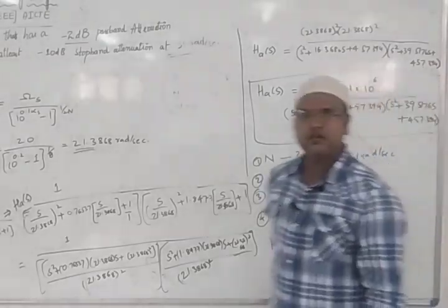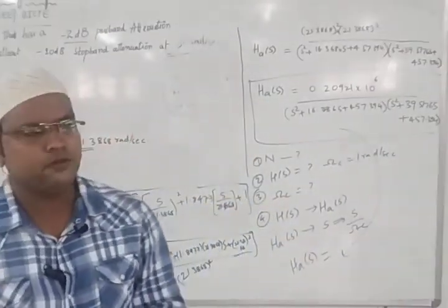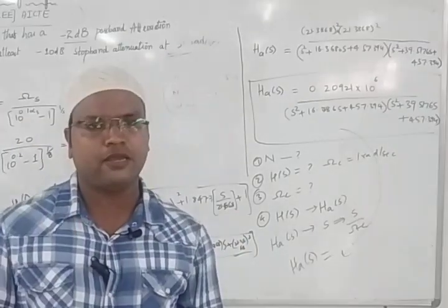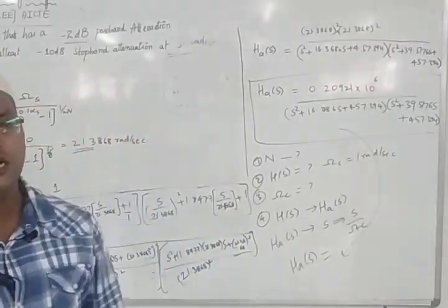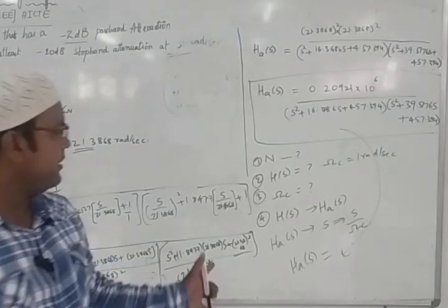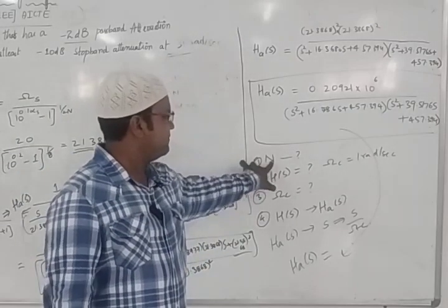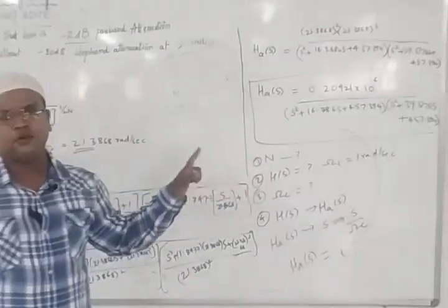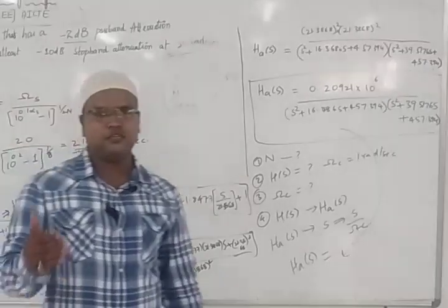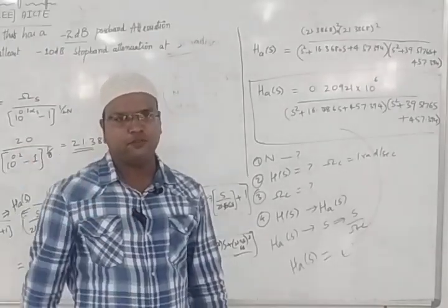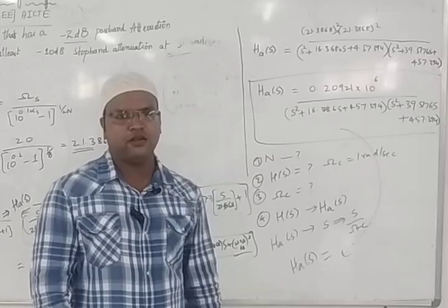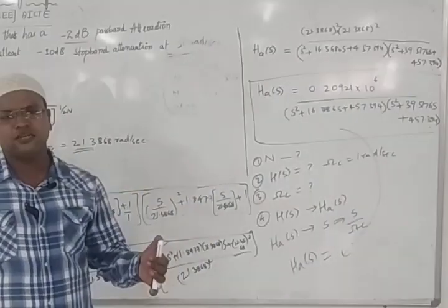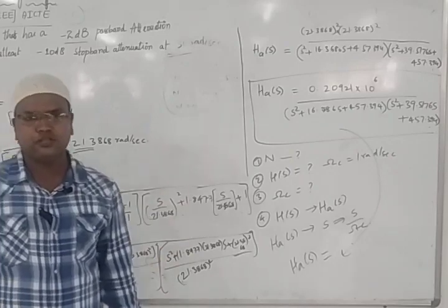So this is the way you can solve the given problem for all types of specification. All these steps you need to keep in mind while you are solving these kinds of questions. So you need to remember the value for your N. How do we get N? By taking the log factor. Log of 10 power 0.1 alpha S in the numerator, alpha P in the denominator, attenuation in stop band, attenuation in pass band, divided by log of omega S, that is nothing but stop band frequency ratio to the pass band frequency.